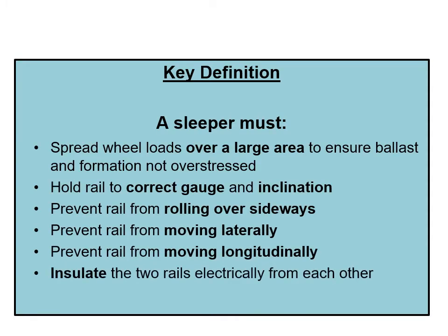A sleeper must spread wheel loads over a large area to ensure ballast and formation is not overstressed, to hold the rail to the correct gauge and inclination, prevent the rail from rolling over sideways, moving laterally, moving longitudinally, and insulate the two rails electrically from each other.